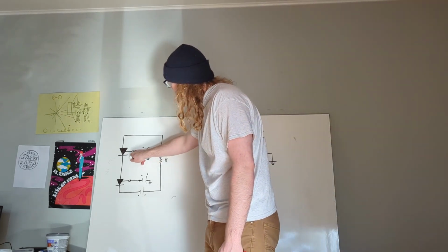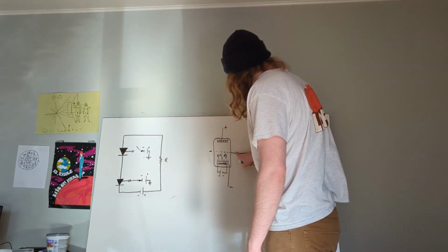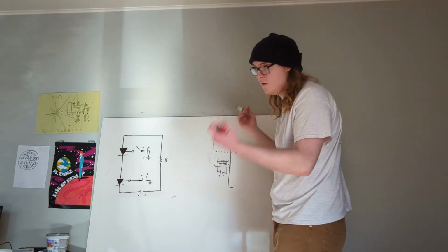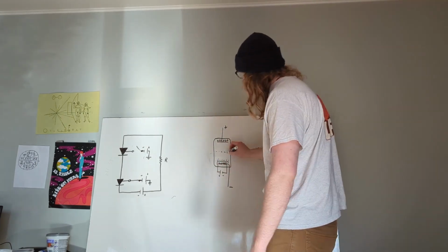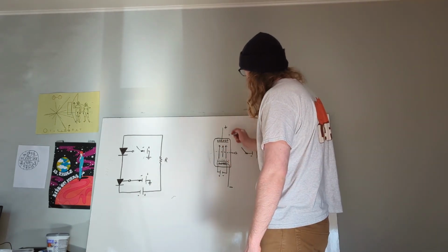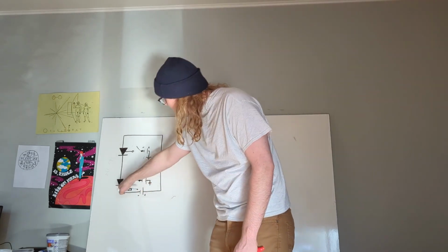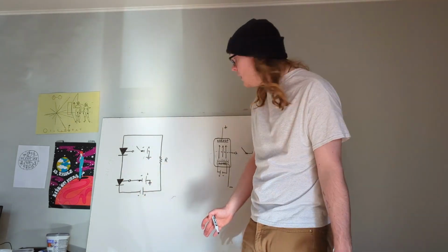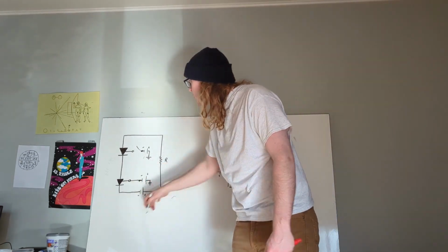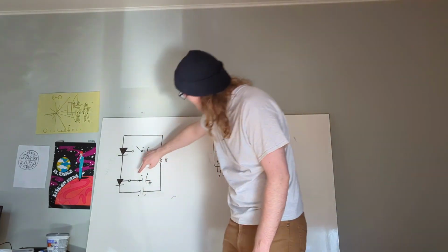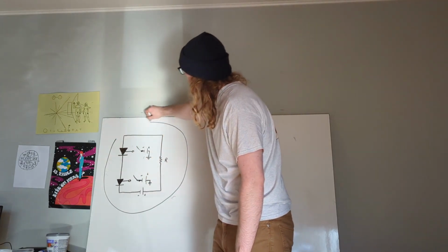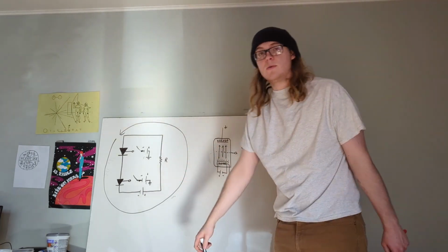Now, when we open one of these, like so, then the voltage across our grid is nullified, and no voltage exists across it. Thus, we have a normal diode in our configuration, and current is allowed to flow via the thermionic emission of electrons from our cathode to our anode. However, because the lower triode still has the negative voltage induced across it, the current through the larger circuit will again not be allowed to flow. However, when we open this circuit too, then and only then is current allowed to flow through our larger circuit and through our load resistor.